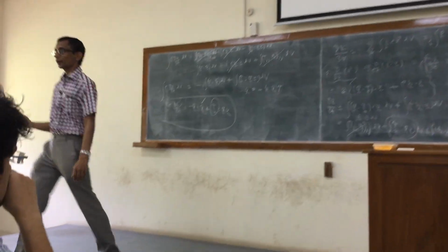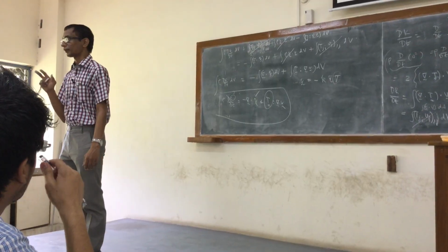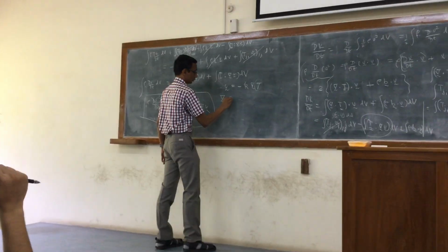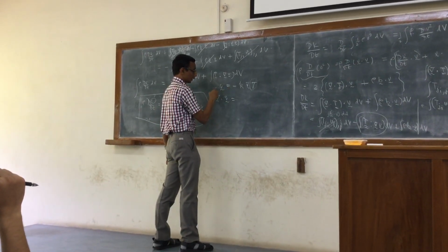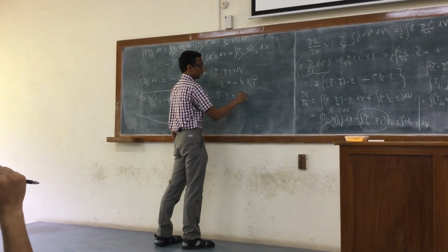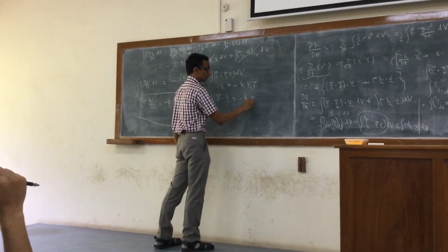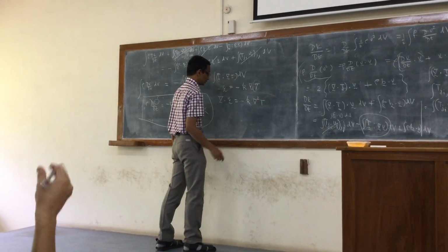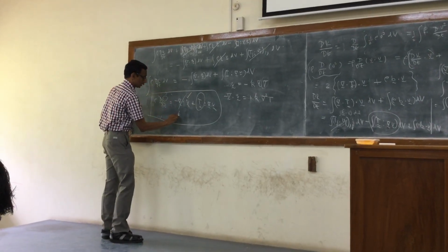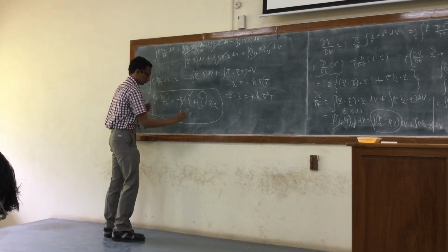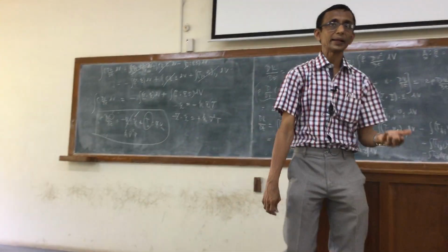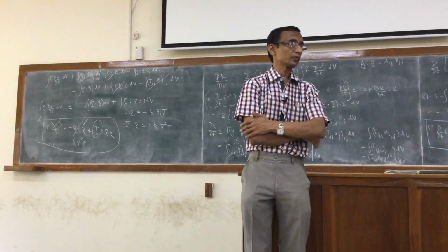If you further consider a linear heat conductor with constant thermal conductivity, then clearly it will become the divergence of this, right? K can be taken out, minus K. The divergence of the gradient would simply be the Laplacian of the temperature. And so minus of this would simply be given by K times the Laplacian of T. K is called the thermal conductivity, which we are all very much aware of.